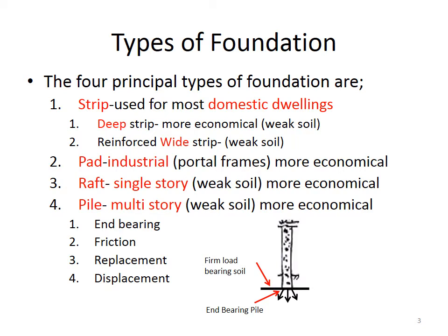An end bearing pile is where we dig down, or we might be digging down through lots of weak soil until we hit a firm load bearing soil. That's the end bearing pile.